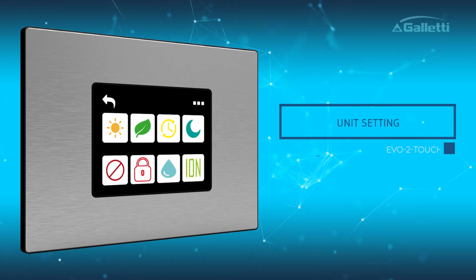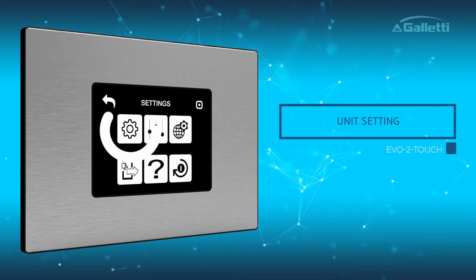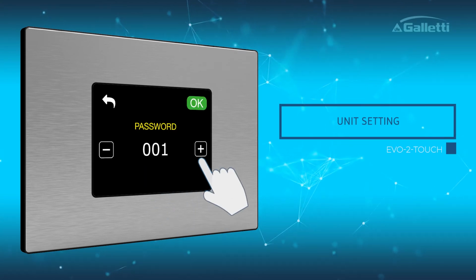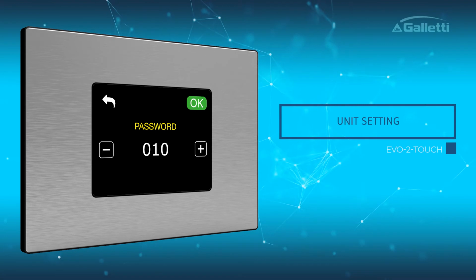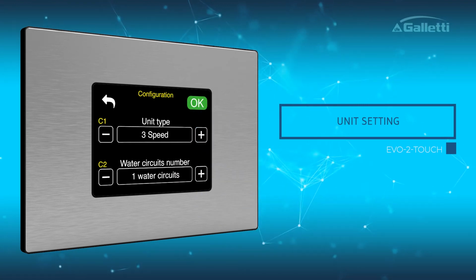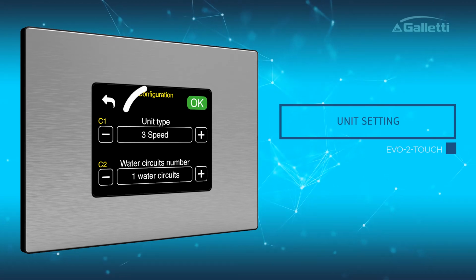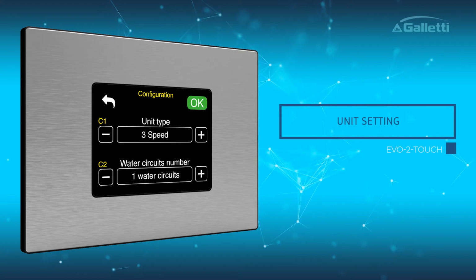From the main menu, click on the three dots in the top right-hand corner. To access the settings, click on the icon on the left and enter the password, in this case, 10. Once the password has been entered, the display shows the settings for the type of fan speed and the number of pipes, either 2 or 4.